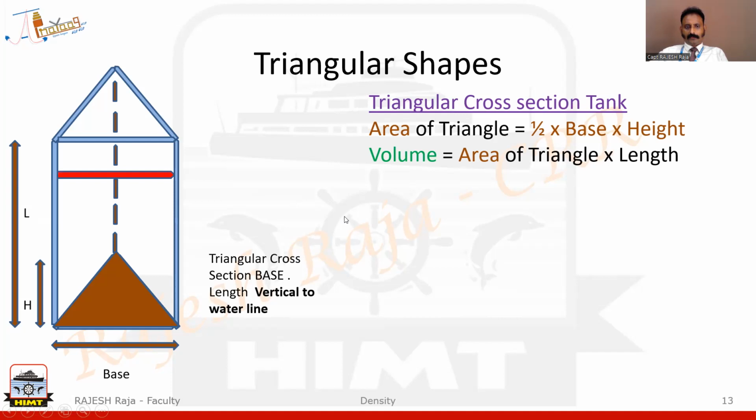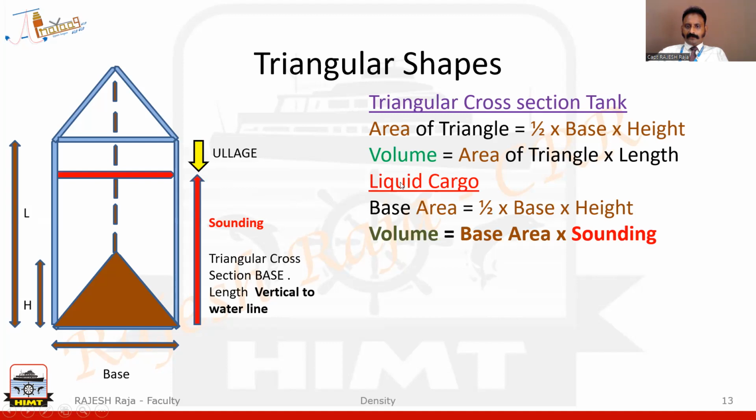Let me fill up a cargo. Again, obviously, the first base area will fill up, then it will vertically rise. So I will have a sounding and an ullage. So if I want to look at liquid cargo, this area is still the same, and volume of that cargo is base area into the sounding.